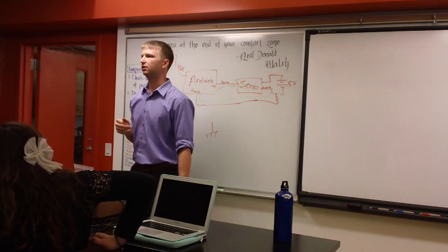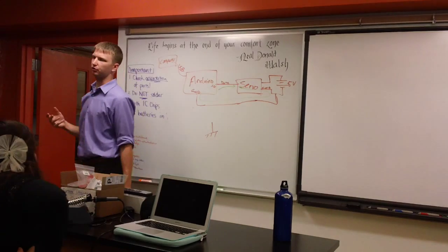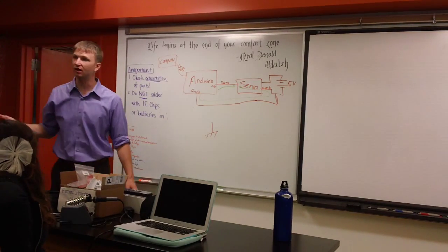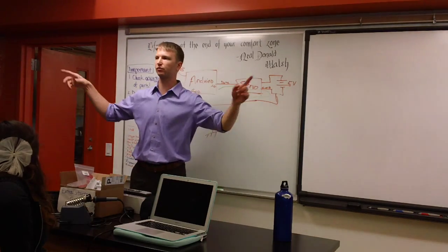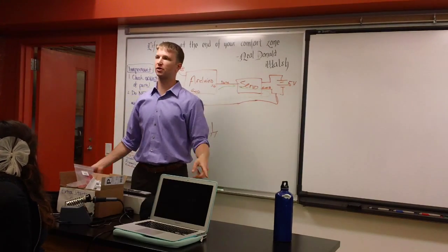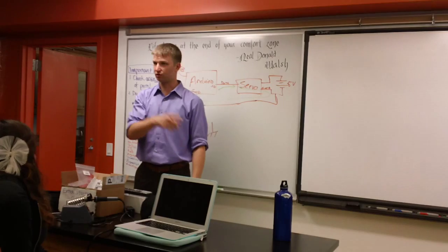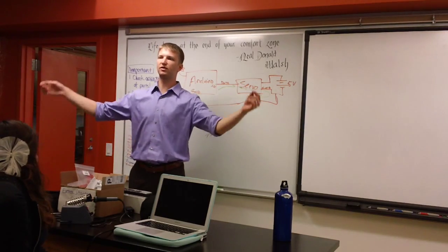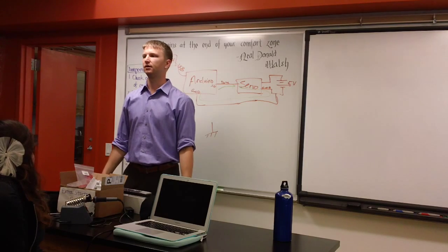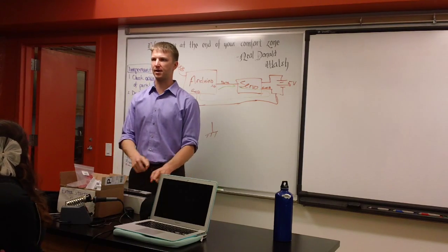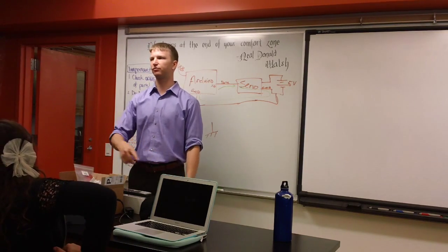And so that's something that people use when they're doing like telephone transmission lines. If you wanted to communicate over long distances and you wanted to run only one wire, because you know wire's expensive, you could stick an 8-foot copper rod in the ground and then use that as your ground, because electricity can flow through the earth.